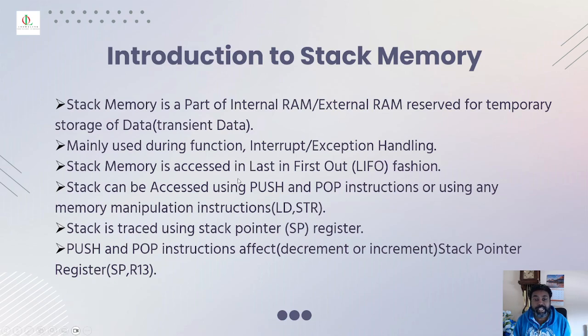The stack can be accessed using two special instructions called push and pop. Use the push instruction to store the data and the pop instruction to retrieve the data. Or else, using other memory manipulation instructions like load register and store register, you can also access the data that way. LDR stands for load, STR stands for store.